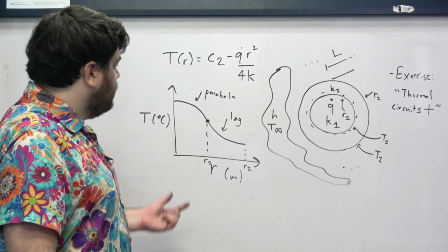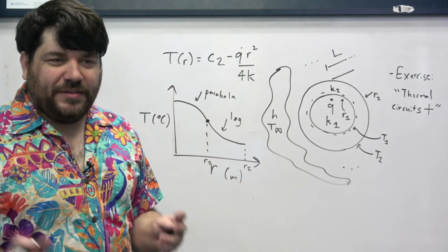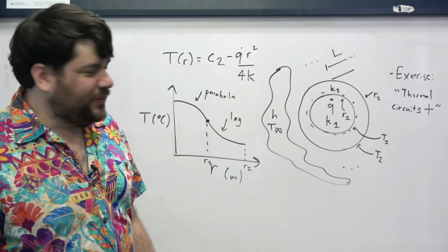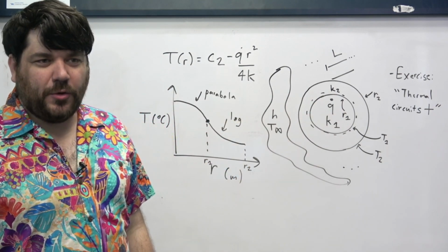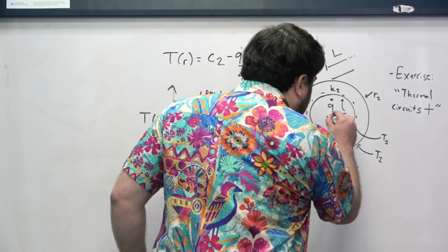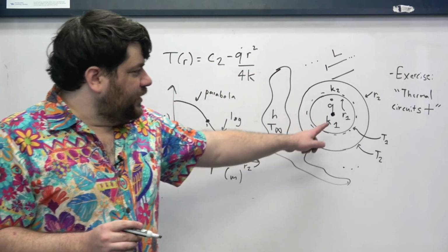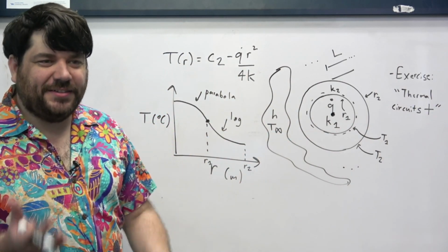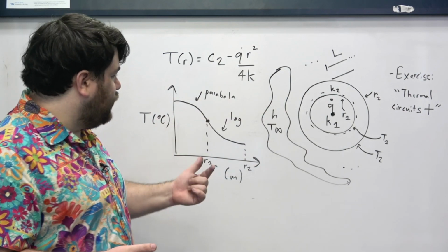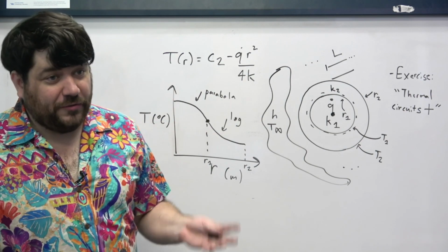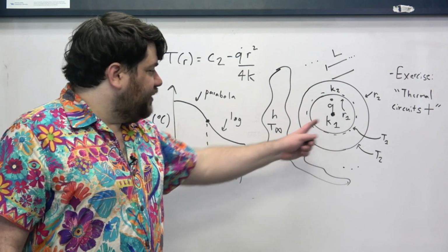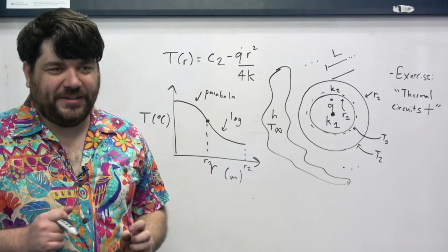goes away. But fundamentally, there's another key physical reason, which is that there is no heat transfer inwards or outwards exactly at the core, right? Because at the very center, at the origin of the cylinder, there is no longer a consistent definition of inwards or outwards. And so as a result, the only way that this kind of approach works is if we say, or observe, I guess, if you trust the math, that the heat transfer rate, the heat fluxes, and the temperature gradients at the very center of the cylinder have to be exactly 0.